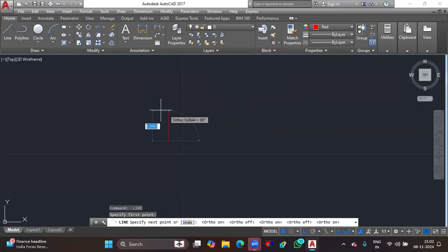So let's continue on to the line command itself. Technically, if you use this command, you can see that I can properly and without any hesitation or misalignment easily draw my line. Now it's about the dimensions. I need a 100 mm line. That means you can directly type the value.